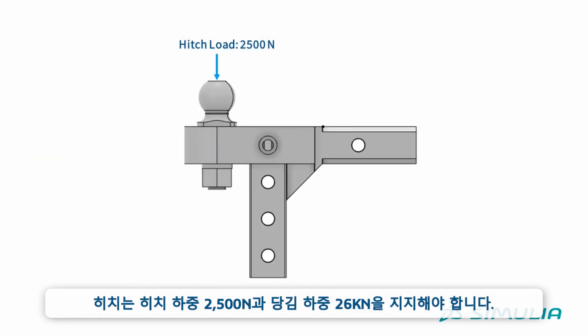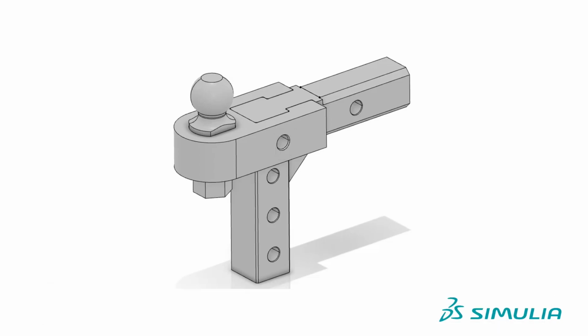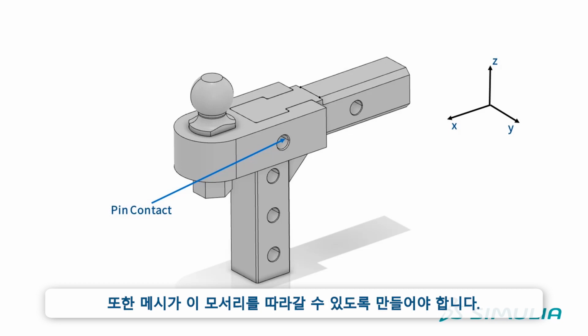The hitch must support a 2,500 Newton hitch load and a 26 kilonewton pulling load. We need to decide how we are going to restrain and load the slotted lug component. First, let's remove the lock pin. We are going to replace the pin contact with the restraint acting in the X and Z directions. This will require us to create some geometry that we can use to create a group of nodes. We will also want to make sure the mesh follows this edge.